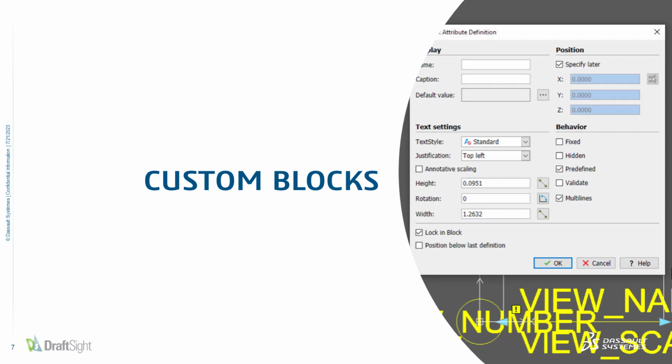Next, with number 4, I'm going to be talking about custom blocks and utilizing custom blocks specifically for labeling purposes, like labeling views, detail callouts, section callouts, things like that. The drafting symbols that you'll use on every single drawing sheet set, dozens of times, maybe even hundreds of times, you can really speed up the process of labeling your views, labeling your details, and even linking tags to the correct sheet using hyperlinks. But we'll go over all that here.